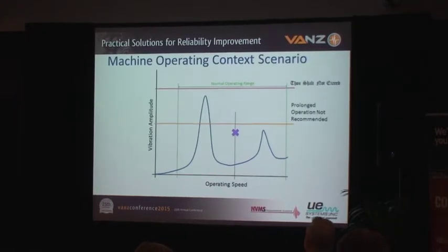But for the more simple approach of putting in an absolute value threshold, where do you put it? Chances are pretty good, and in my experience at the plant that I worked in, it was the thou shalt not exceed criteria that the control room focused on. They would focus occasionally on the lower criteria where we say, we don't want to run more than like 10 minutes at this amplitude. But what about when we're running in the middle? We could have a serious problem at that particular point on the operating curve, and the alarms wouldn't even come in.